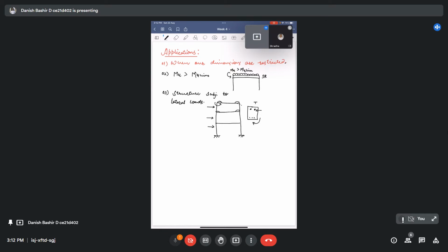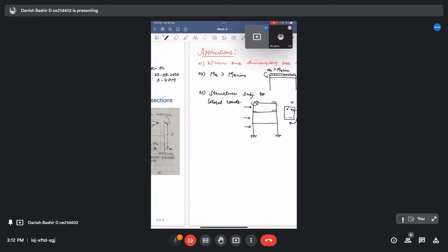To prevent it, we also provide the compression steel at the top, whose primary objective is to add compression strength to that section. But in addition to it, it also provides tensile strength on that side when it is subjected to the hogging moments. So now I directly come to the design formulas.